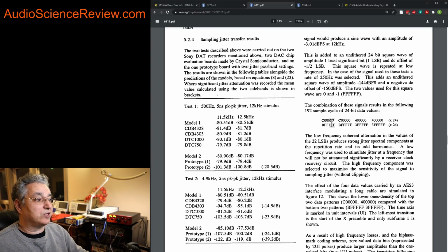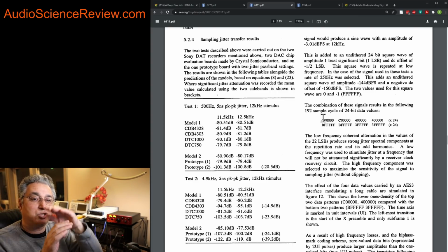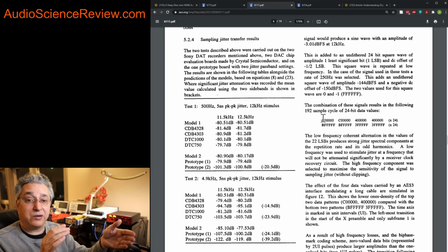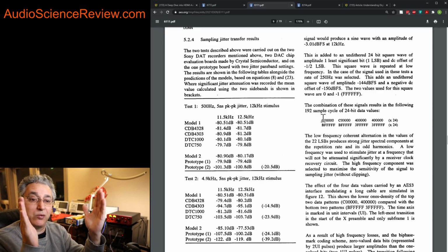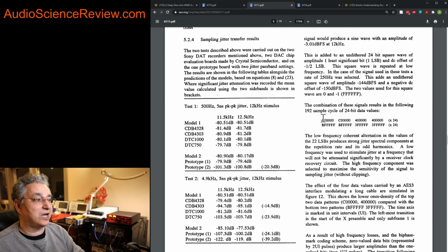So indeed, if we have a 12 kilohertz square wave, but we chop off everything above 24 kilohertz, which is the bandwidth that we have in a 48 kilohertz sampling, everything gets thrown out and we wind up with a pure sine wave. And all we had to do digitally, if we look inside of the signal, which is called the J-test or jitter test, all it has is a square wave in it. That goes from this to this.